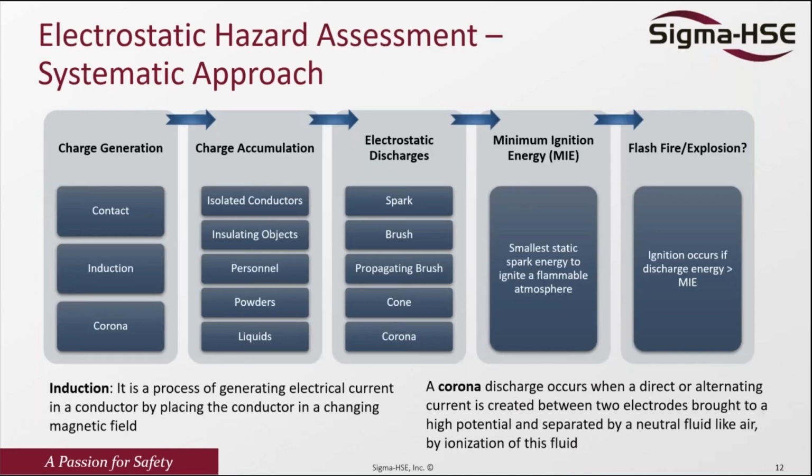So how do I assess electrostatic hazard? The first thing that comes to my mind is I need to understand how this charge is generated. How does it accumulate? How do I dissipate or discharge it? What are the key parameters that I need to know when I have this discharge? And what is the energy that can ignite the material that I handle?